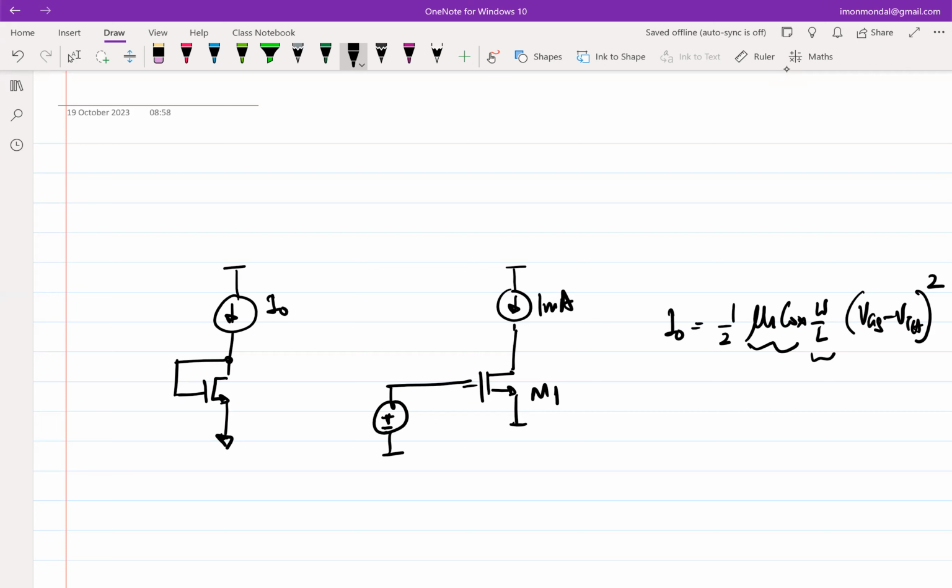Now, what is fixed? These guys are fixed. Threshold voltage is fixed. So if I can only apply this battery to be exactly equal to this VGS, then the right-hand side and the left-hand side of the equation are balanced, right? So then there should not be a problem. Then the transistor M1 would be perfectly sinking the current of 1 milliamp, right? So as far as the mathematical balancing of equations is concerned, this is fine.